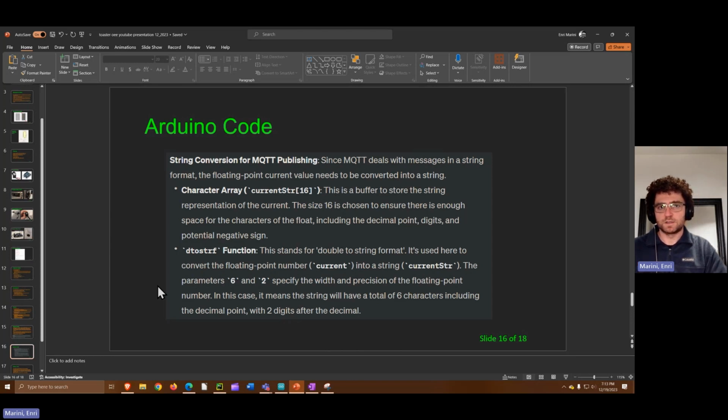Keep in mind, when you do this, you do run into an issue where you could potentially damage your analog input, because not only does the burden circuit serve to provide you a voltage value, it also acts as a buffer to protect your analog input from getting current values that will potentially fry the circuit. So I guess what I'm trying to say here is that I took one for the team, and I did this on my board.